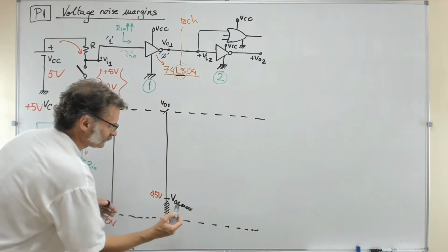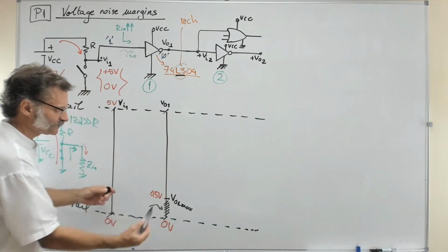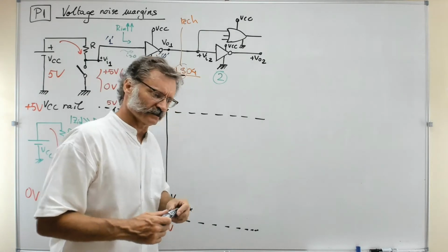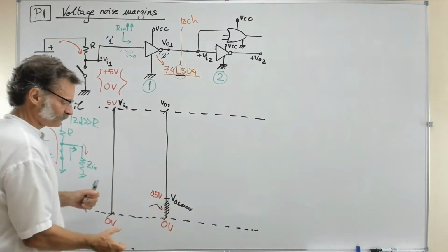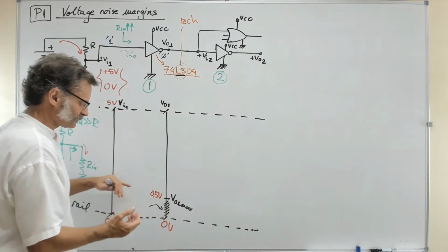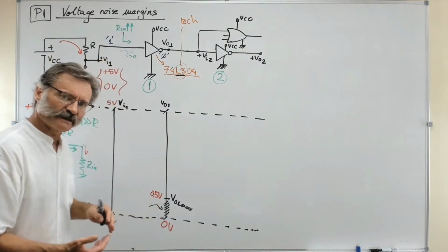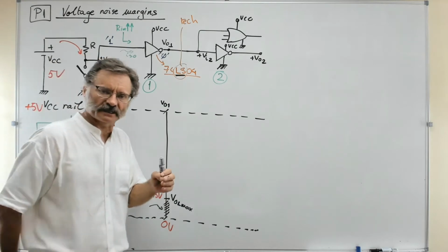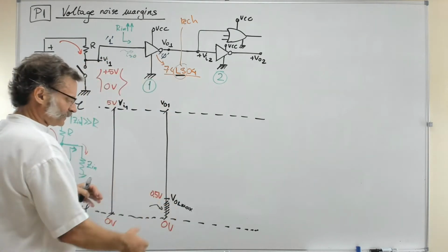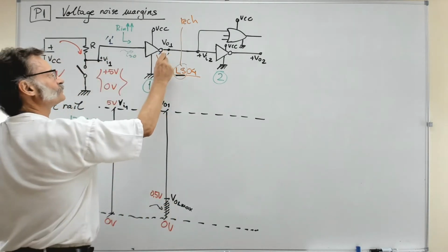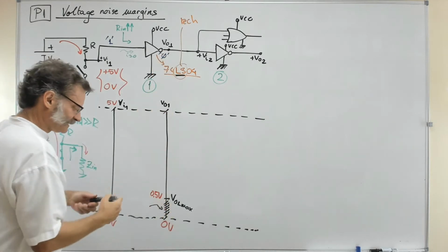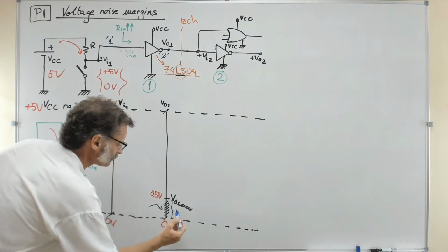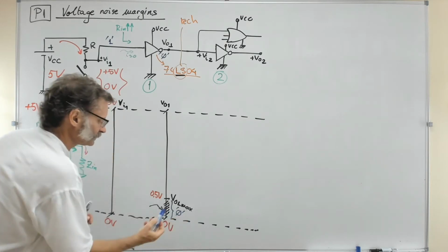So normally the typical value is going to be in between this, but the manufacturer admits, or the convention, or the people who decided to organize this technology said that you may expect a maximum value of 0.5 for certain gates, for example. So that's the point. So when you talk about the zero at the output, what you get is this margin, right? Look at this. You have a margin of values that are all interpreted as a zero logic.